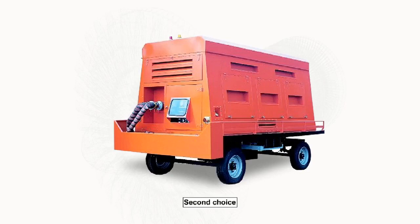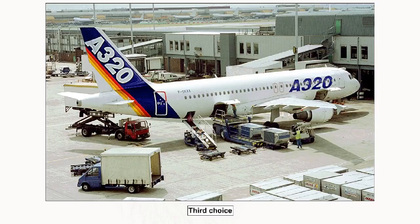The Ground Start Unit. If a ground start unit is required, perhaps because of APU unserviceability, the airline will have to pay for its use. This is understandably not too popular with the airlines. A crossbleed start, where air from an already started engine is used. A crossbleed start doesn't cost the airline anything, but it does require that the engine that supplies the air has power applied to it. In the crowded environment of the ramp, applying power to an engine carries obvious risks, and some airport authorities are reluctant to give permission to the pilot to carry out this type of operation.